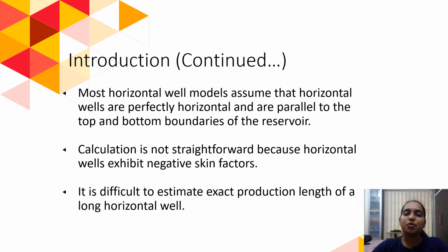Further, it is much more difficult to interpret well test data because of 3D flow geometry. The radial symmetry usually present in a vertical well does not exist. Several flow regimes can potentially occur, and more significant and partial penetration and end effects commonly complicate the interpretation.